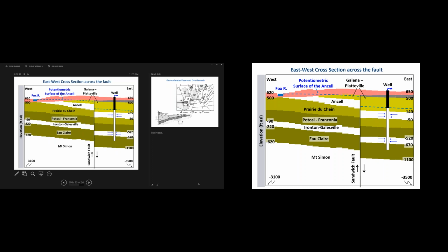So if your model grids are vertical like this, it sees this as one unit, just like it's over here. Yeah, even though our grids don't match. Right. So when flow leaves here, it's going to come in down here. Even though this is all, say, a big hunk of till, and this is sand, and this is till, this flow goes into here, this flow goes there. So they're disconnected in your model.